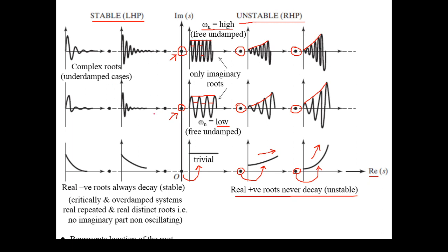These responses are always stable, okay. So if you look at this root, it is much closer to zero, but it has a negative real part because it is plotted on the other side of zero. No imaginary part, but only a negative real part. So it is of decaying nature, but it will take some time before it comes to rest because it's not a big value. It is much closer to zero.